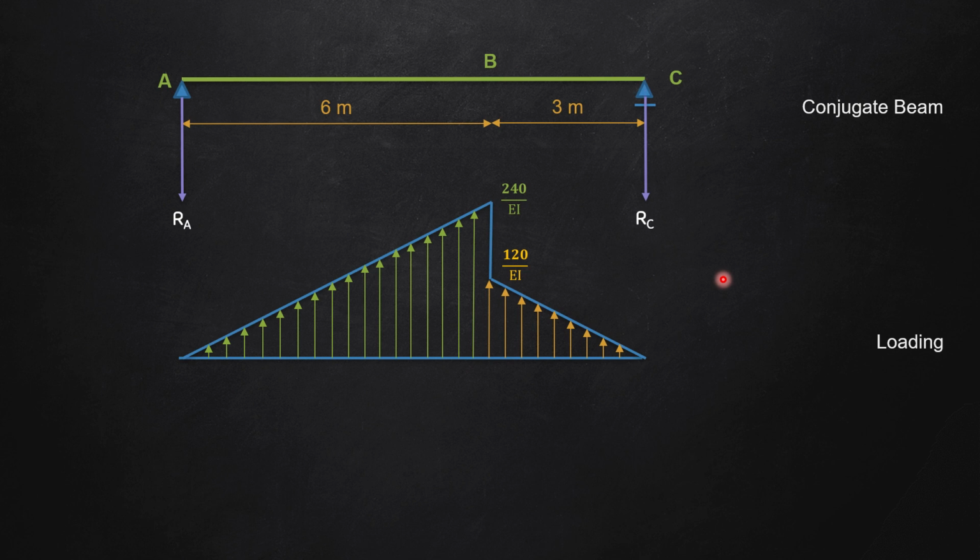In lecture 2, where I had solved the cantilever beam, this step was skipped because I could easily go from the free end and keep on finding the moment without finding the support reaction. But here I have no choice but to find out the support reaction since none of the ends are free. Alright, now how will I find out the support reaction? Same way, I'll be using the equations of equilibrium.